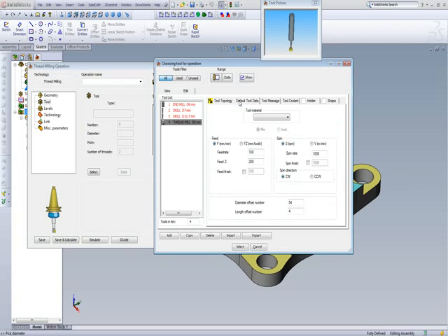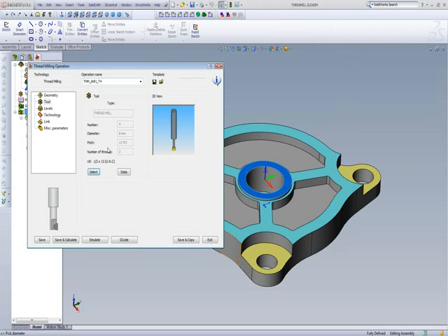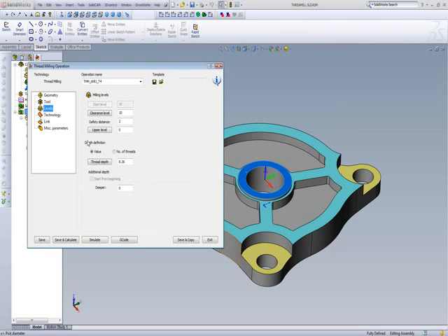In the default tool data, the data is exactly like any other end mill. I'll simply select my tool, and then we'll go to our levels. We have our upper level on the top over here, and then we have our depth definition. We have two ways of defining our depth definition. One, either the actual depth of the hole itself, or the amount of threads I want on the wall itself. Either way, whichever one is necessary.